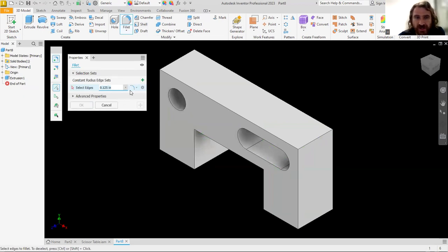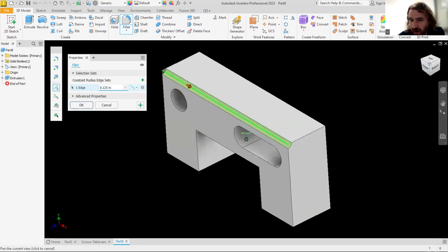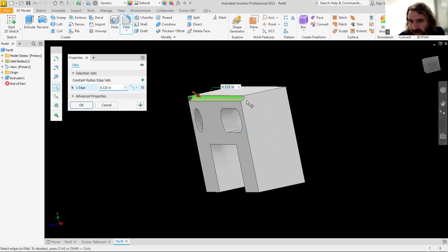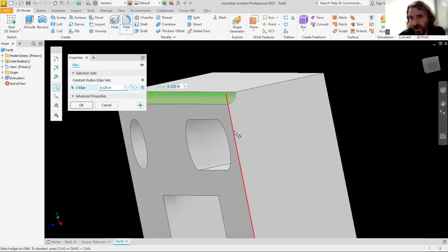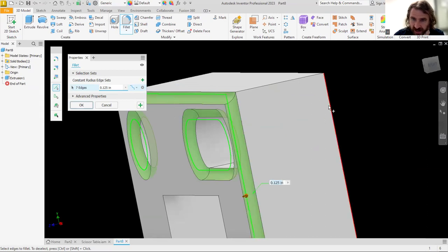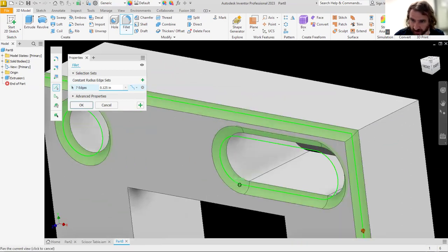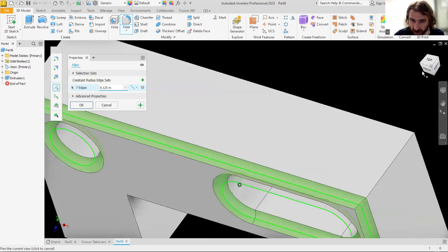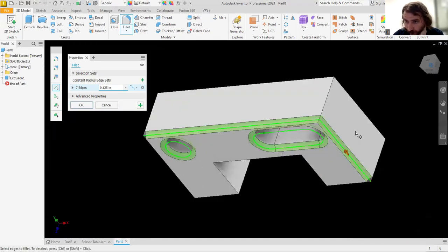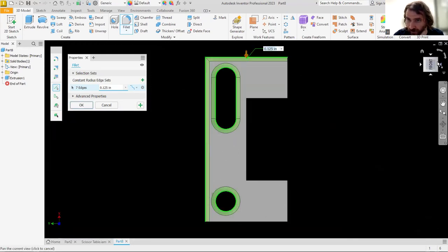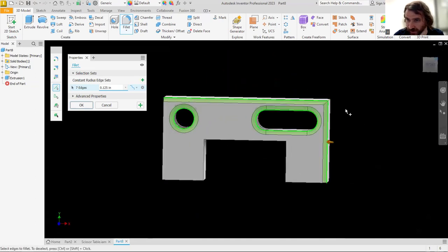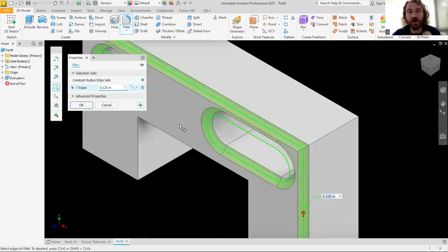The other idea is, instead of a fillet that's rounding a corner like that, you can have it go inverted. It's still rounding the corner, but it's cutting that distance into the part. So this is a different kind of scenario, right? If we click on all these again, it's going to do the inverted fillet. The invert is cutting material out, kind of the opposite of what it was doing before. I'm all lost here in the view cube. There we go. Now we're feeling better, right?